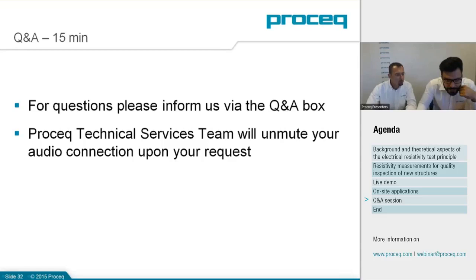Okay. Now, does concrete cover change the resistivity? We covered that earlier as well. No, it will not, basically. Is it possible to make a measurement on a 15 centimeter sample cube? Not a standard sample, but technically it's possible, and you can compare the results on the same samples.